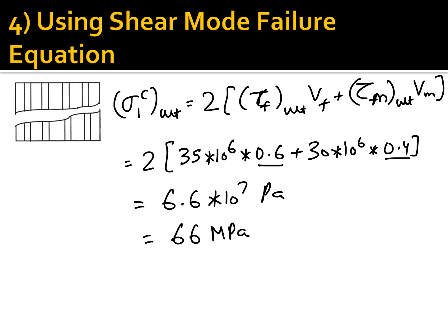So we basically have calculated the value of the ultimate compressive strength here in direction 1 by using 4 failure modes. So we want to find out here what is the minimum of those. So we got 795.8 through matrix failure. We got 13870 because of the extensional microbuckling load.